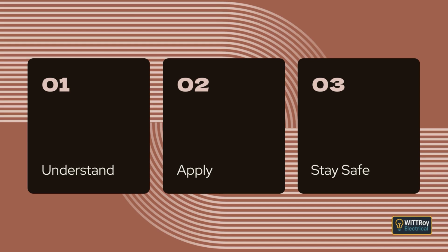Clause 2.3.4.1 Electrical installation in an outbuilding. This clause explains that an outbuilding can be treated as a separate electrical installation. If the outbuilding has a maximum demand of around 100 amps per phase, or if it has its own switchboard, then it must be treated separately.